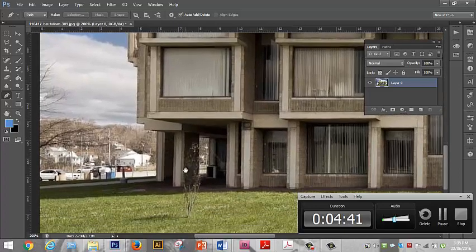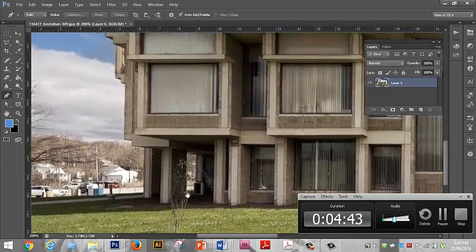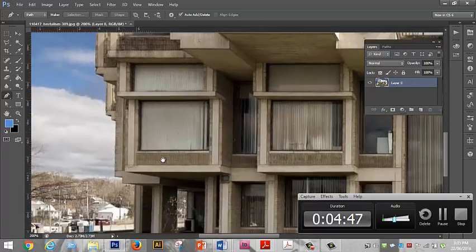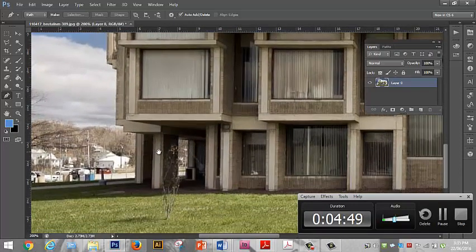Now, let's begin. So zooming in, Control plus, zooming out, Control minus. And if you press the space bar and left click and drag, you can actually move around nice and easily, and this is really important. So the space bar changes the pen tool into a little hand. I'm going to put it so we can see it. There you go.